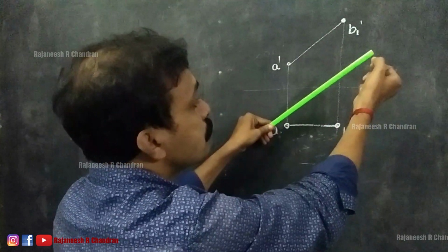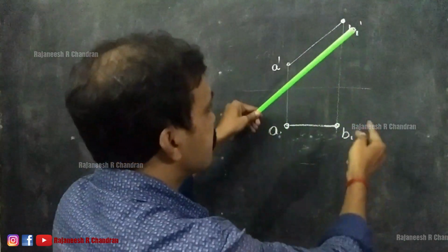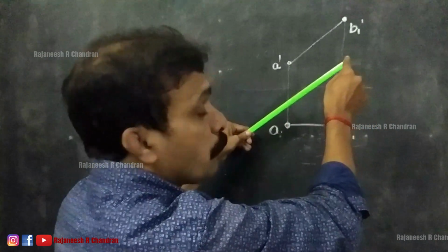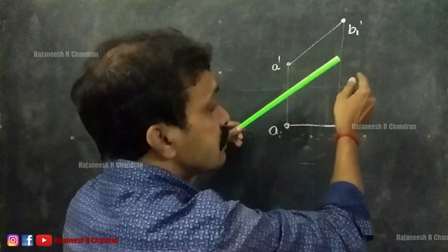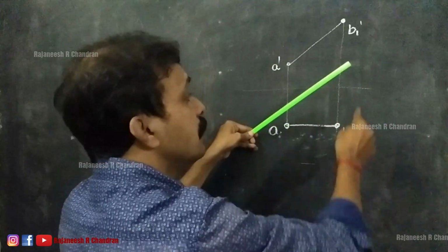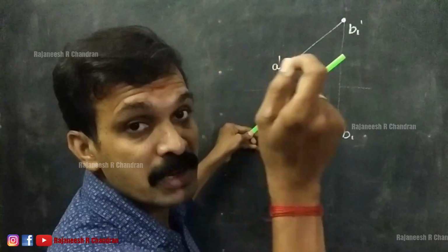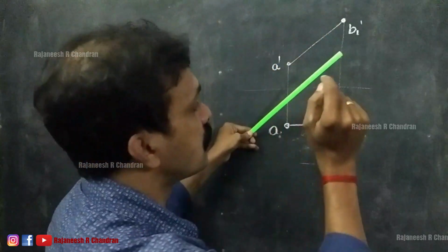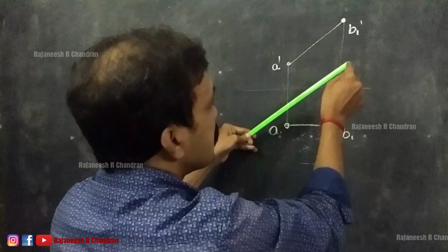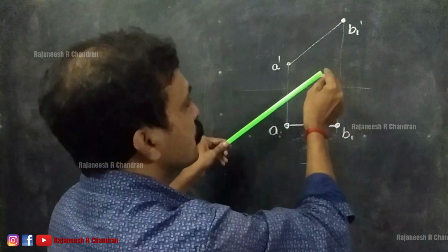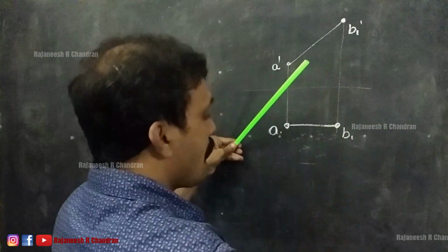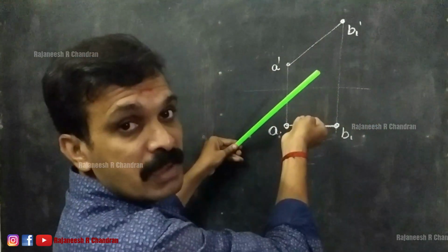So what will happen to this point? Since the height of elevation is constant, this point will be moving along a line. See, this was the initial position and we are rotating into this position by keeping this height constant. When we observe this process from infinity, we can see that this point will be projected here, and while rotating this line, since this height is the same, this point can be observed as moving along a line as this height is kept constant while rotating.